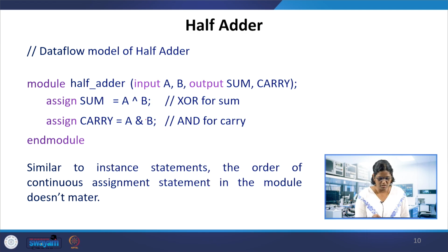Similar to instance statements, if you have multiple assign statements inside the module, the order of continuous assign statements doesn't matter. If the input is changing, the last statement may change first, and then that needs to be updated in the first statement. It is very well handled by the simulator. It's updated. These are concurrent statements.